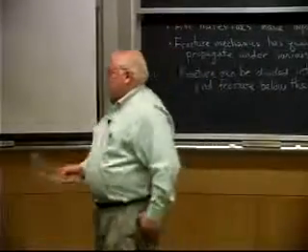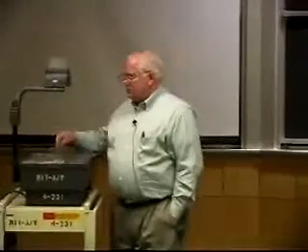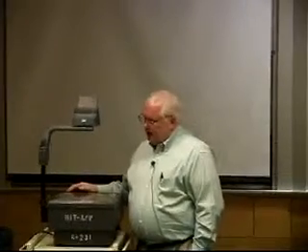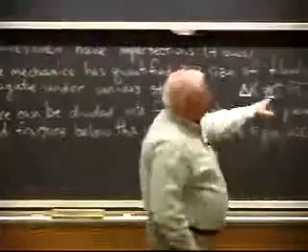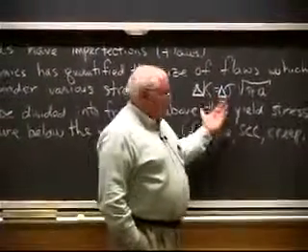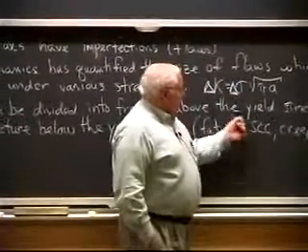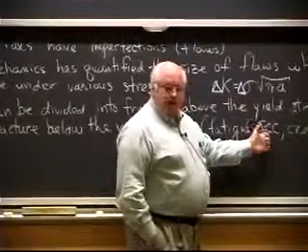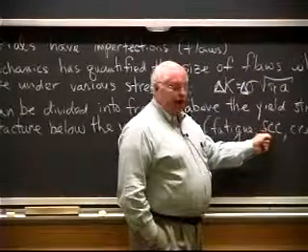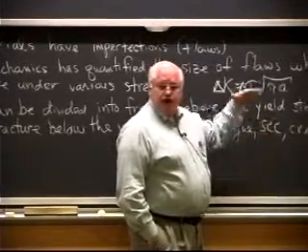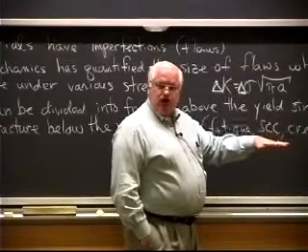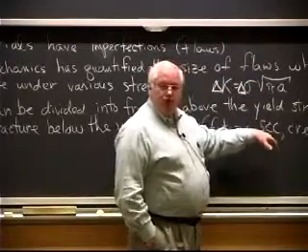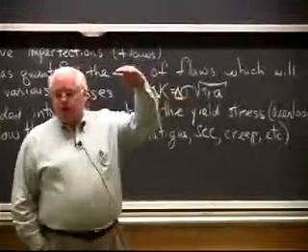One of the things that causes lots of failures, and people don't often think about, is the fact that parts can have residual stresses in them. So they design for a low enough stress that they shouldn't get fatigue, but something else happens. In the case of that washer in the helicopter, that was stress corrosion cracking. They didn't have just the fatigue stress limit, they had corrosion going on, which dropped the fatigue stress.